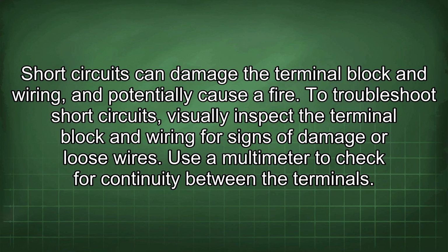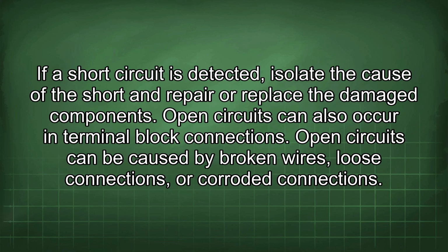To troubleshoot short circuits, visually inspect the terminal block and wiring for signs of damage or loose wires. Use a multimeter to check for continuity between the terminals. If a short circuit is detected, isolate the cause of the short and repair or replace the damaged component.